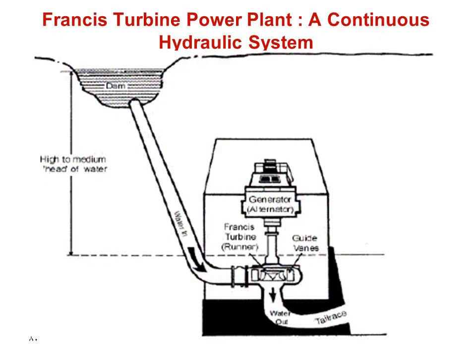As we see from this sketch, the water is coming through a pipeline from the storage area behind the dam, and then transported to the casing of the turbine, and then radially goes to the runner through the guide vanes, and after gives its energy to the turbine. It is converted into mechanical energy, and this mechanical energy is converted in the generator to electrical energy.